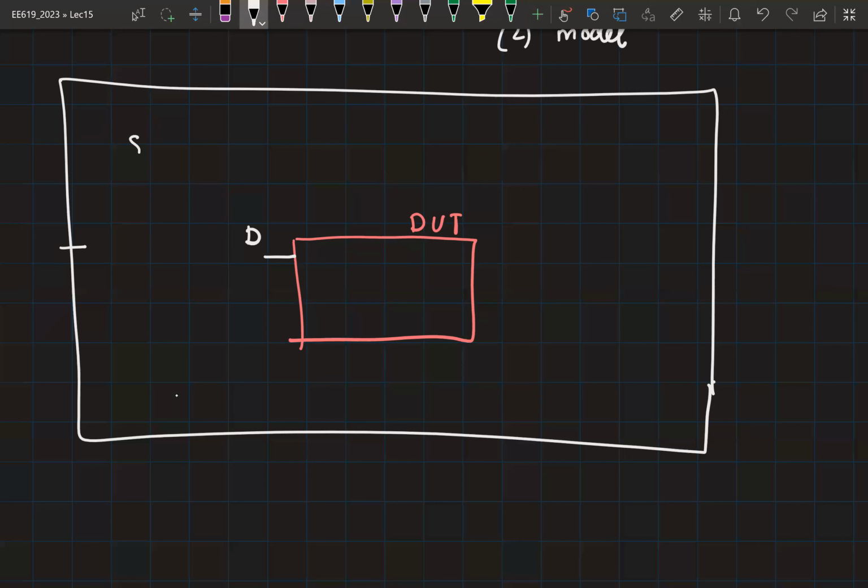So you have commands like $fopen, $fread, $fwrite, etc. Again, non-synthesizable commands. But this will allow you to open files in your PC, read data, run it as an input to your DUT. Then you can dump the results again into another file using $fwrite. So you have all this flexibility when you are working with these non-synthesizable codes for verification purposes.